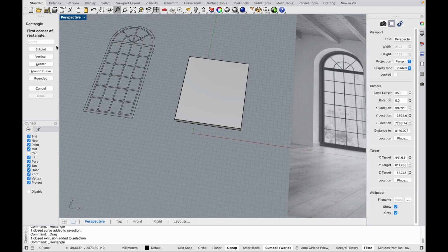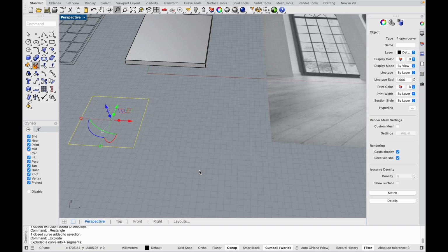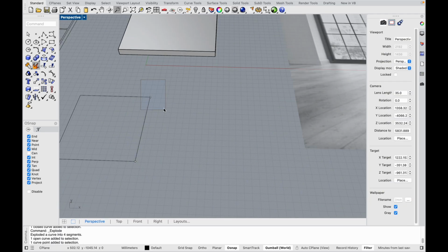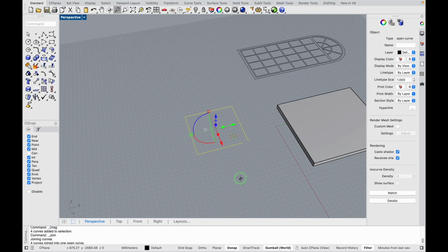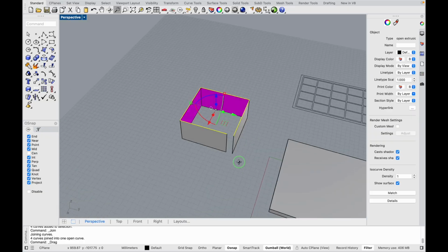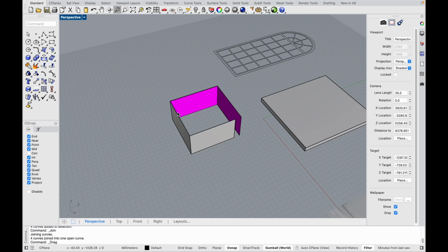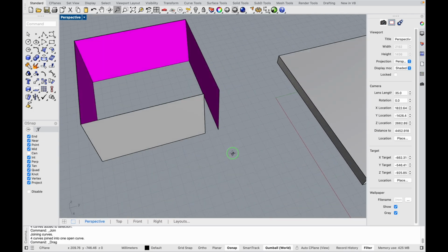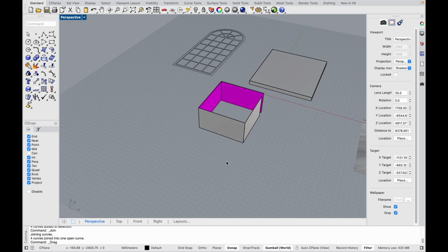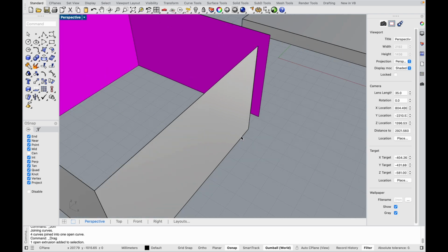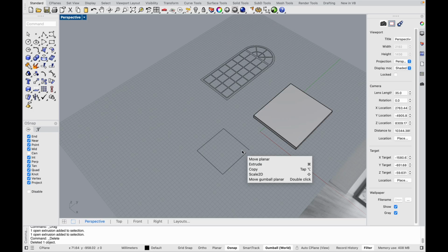But if we draw, for example, a rectangle, but let's make a small hole in it. Let's explode it, select this line, and let's move its end like so. And let's join it again. And let's extrude. This will be the result. So here we have a hole, and we cannot close these parts of the shape, because here we don't have any line which connects this face, this plane. So this hole can be very, very small and give you such problems. So it is really important.